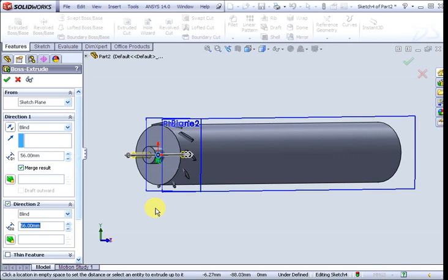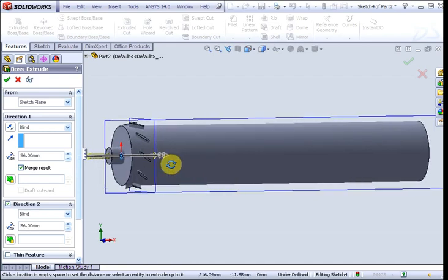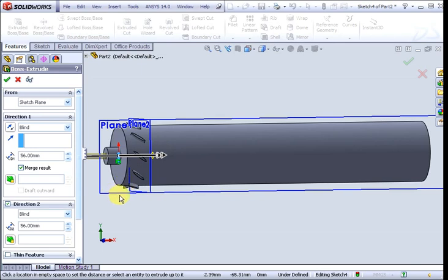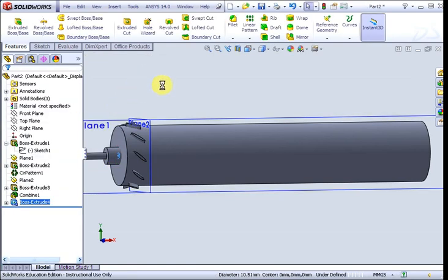Now we remember last time this plane was 35 mm far from this 0 coordinate, so we have to go slightly after that, so the injector will start injecting after the burner, after the swirler, sorry. So we can choose the second one, 40 mm, 5 mm after the bush end or edge. Okay, so again unmerge, so this is a third body here. Okay, now what we want to do is subtract.